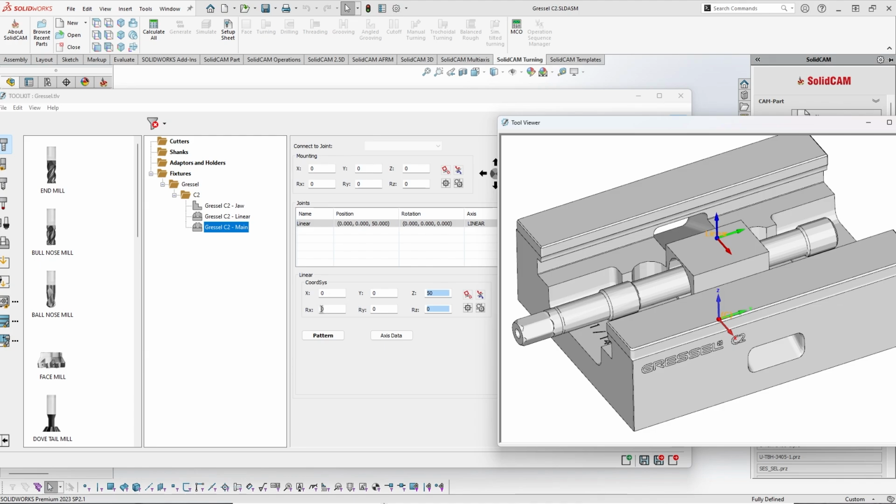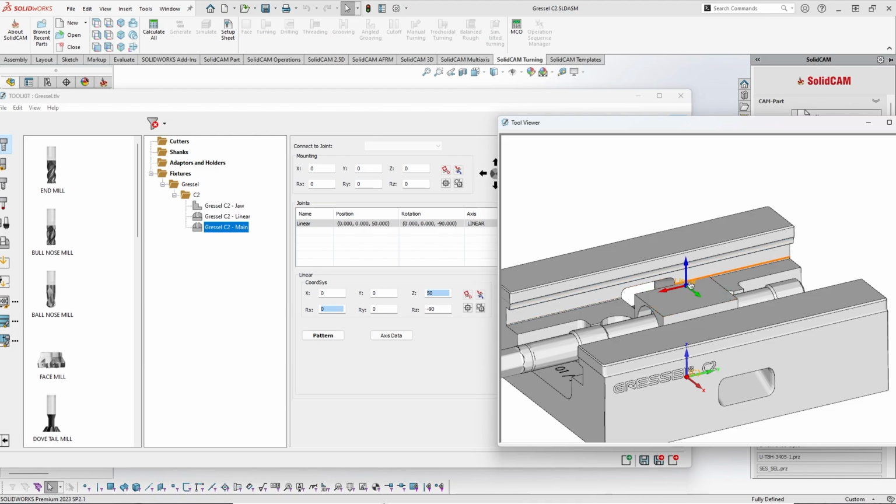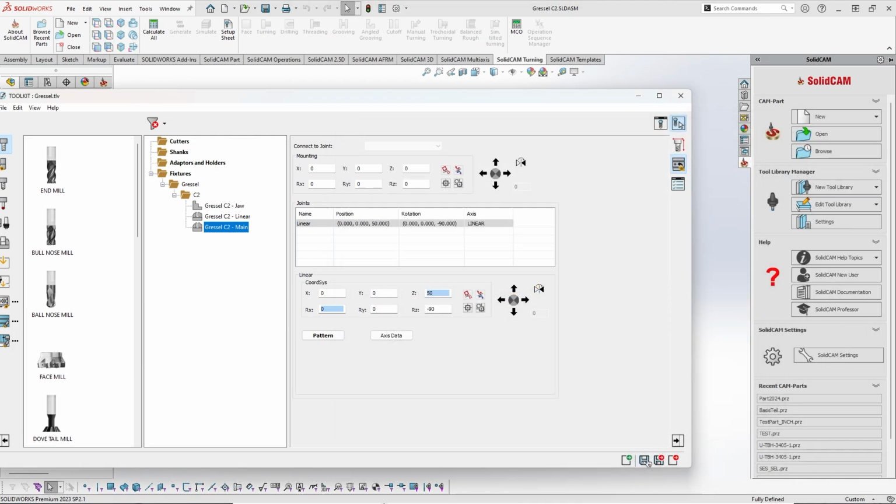So what is necessary to do is just click on this X vector and just click on this surface. It's going to make it normal to that. So as you can see, it's applied. But if you want to flip it, you click it again and just click on the same surface again. And there you go. I think it's a good example that I showed.